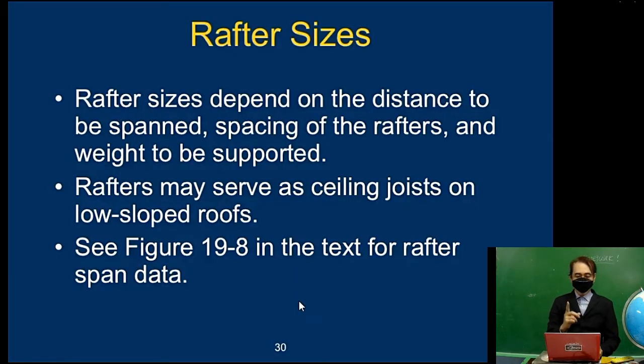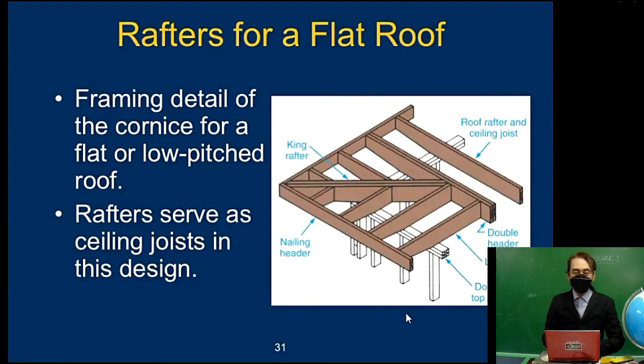Rafter sizes depend on the distance to be spanned, spacing of the rafters, and weight to be supported. Rafters may serve as ceiling joists on low slope roofs. So let's see this figure here. King rafter here. Ceiling joist. Header, nailing header.